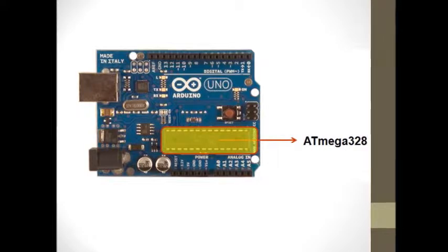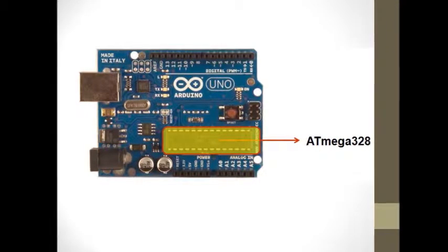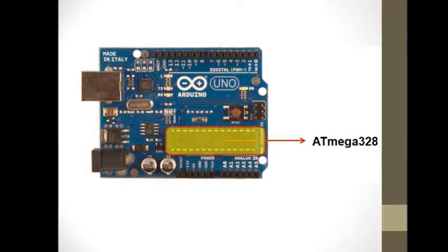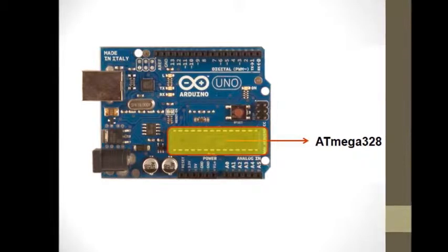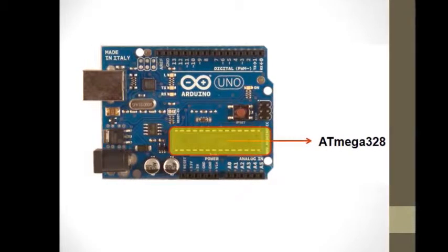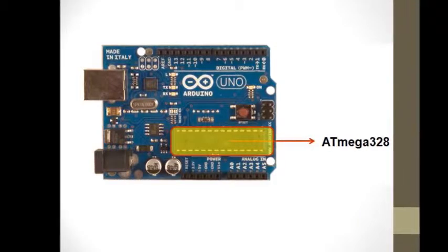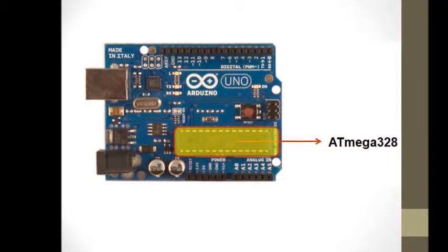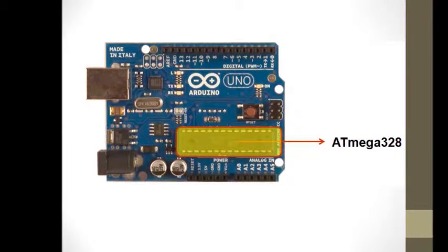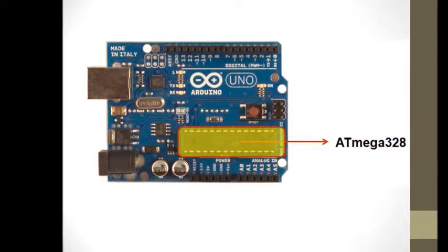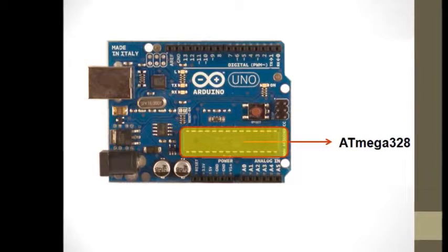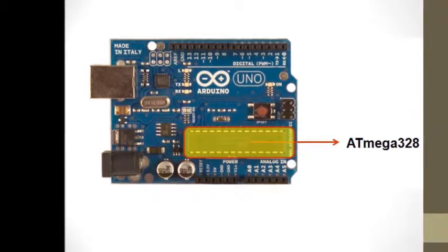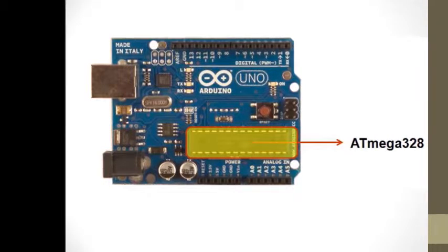Arduino Uno is a microcontroller board based on the ATmega328. A microcontroller is a complete microprocessor system integrated into one chip, designed to obtain the maximum functional self-sufficiency. The microcontroller includes, in addition to the calculation unit, also the memory, RAM and ROM, and additional input-output devices, depending on the specific application. Arduino contains also everything needed to support the microcontroller.